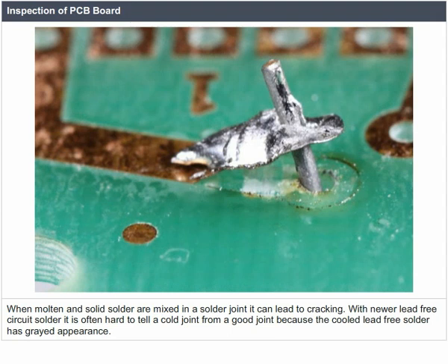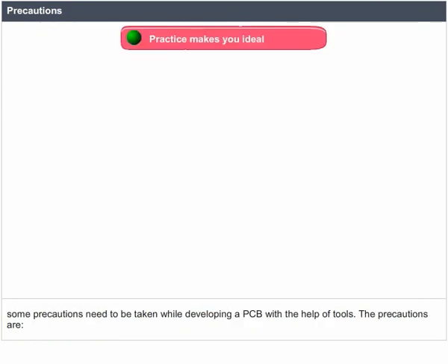With newer lead-free circuit solder, it is often hard to tell a cold joint from a good joint because the cooled lead-free solder has a grayed appearance. Precautions. Some precautions need to be taken while developing a PCB with the help of tools.